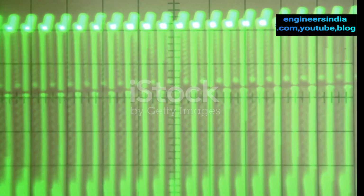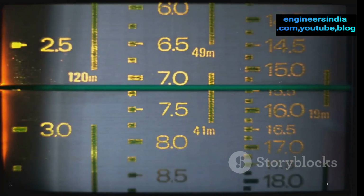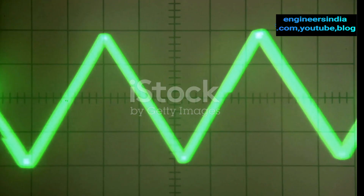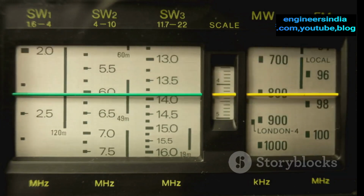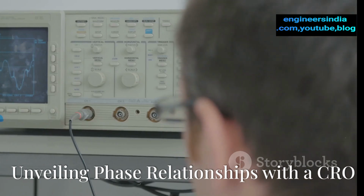Now measure the time period, T, which is the time it takes for one complete cycle. Calculating the frequency, f, is a breeze. It's simply the inverse of the time period: f equals 1 divided by T. For example, if the time period is 0.01 seconds, the frequency is 1 divided by 0.01, which equals 100 hertz. Easy peasy.